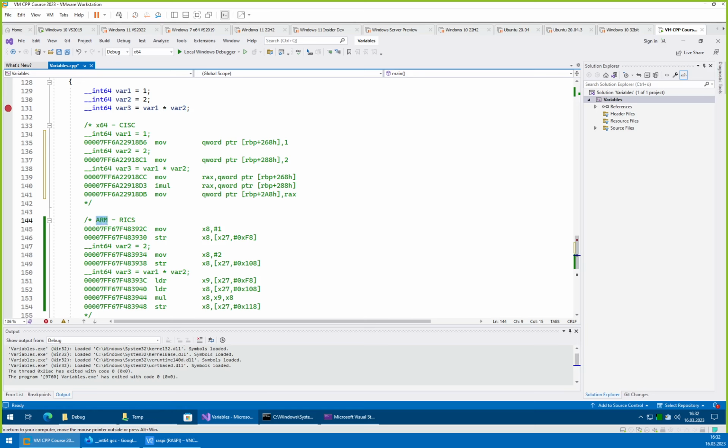So the ARM CPUs, which nowadays also do to some extent speculative execution, they do by far not need to do it to that high of an extent. And also if they have to discard some of the results, it's less, because you have more individual operations. So it's likely that you will have to throw away less of your data if your speculation was wrong.